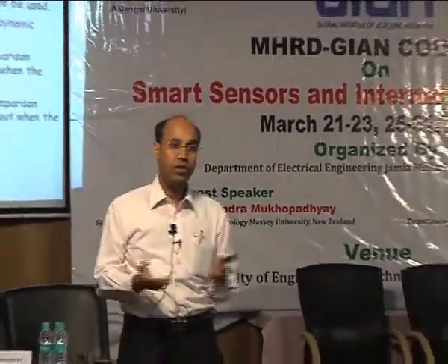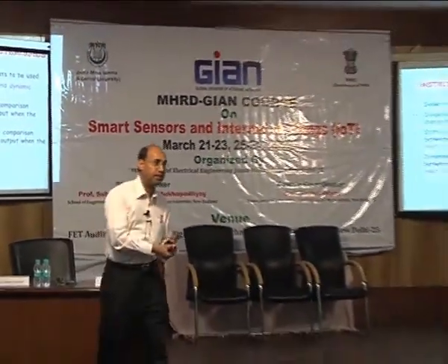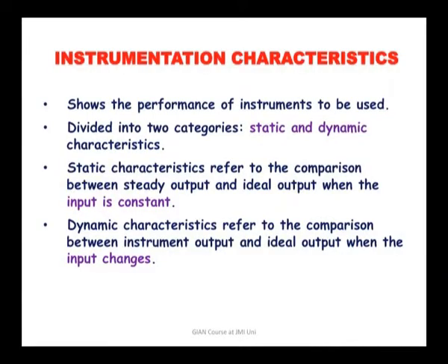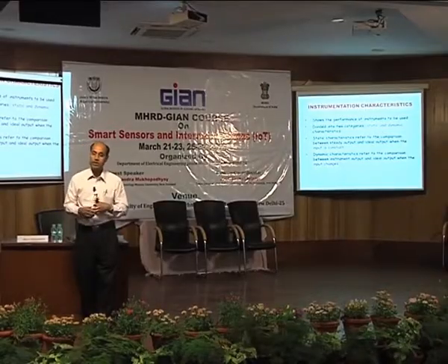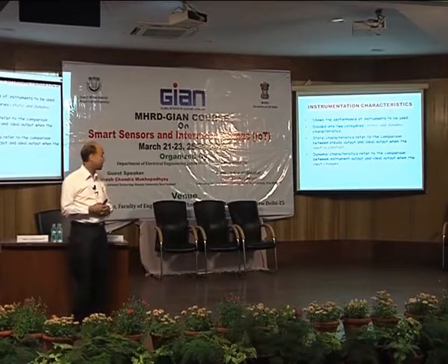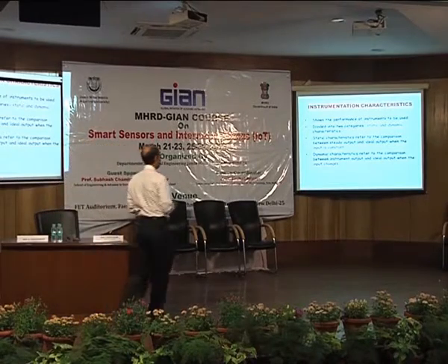We have to know all these things, especially for gas sensing applications. You will always find that it does not give you a response very quickly. There is always a delay, and if the gas concentration changes very quickly, then you will have a problem if you have too much delay. But we need to know the sensor characteristics.